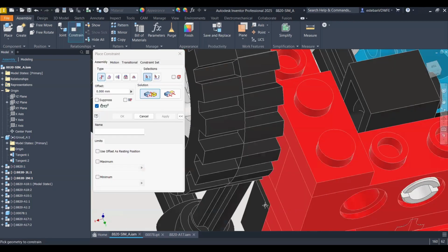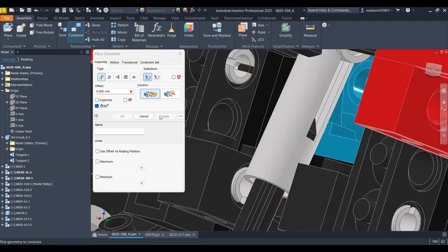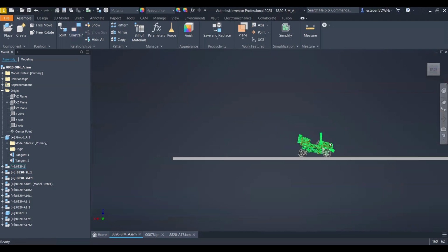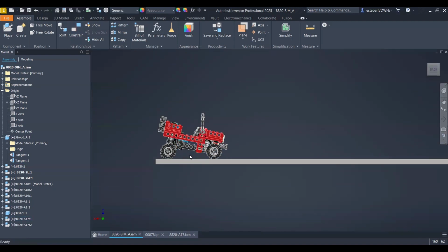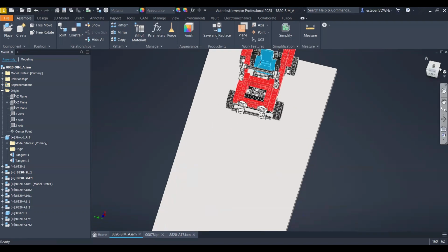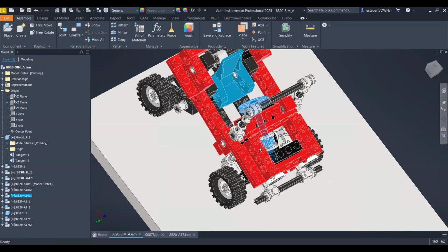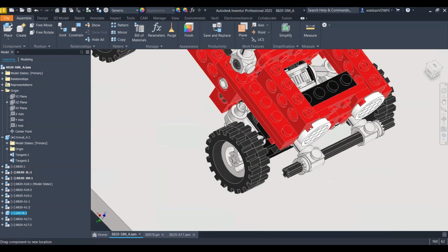In order to get the car in position, you can add this mate of 19 millimeters between faces. That is the one for the spring, as we saw in the second video. We can then drag and leave our car in the correct position.